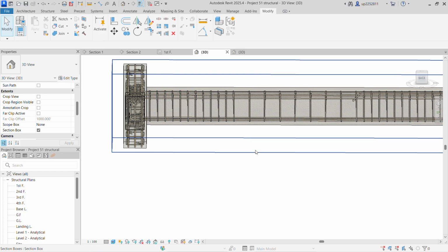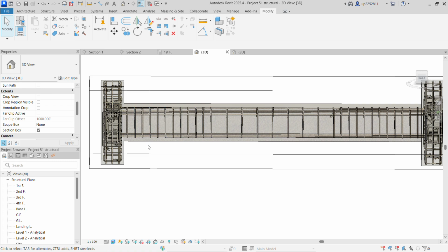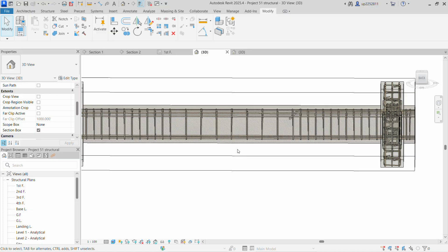That's why we are going to keep minimum distance here, and in the mid section the crack will appear at 90-degree angle. So these stirrups can't prevent that. That's why we are going to keep these stirrups here as a binder, supporting the main bar,